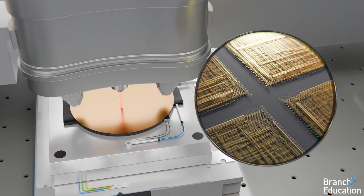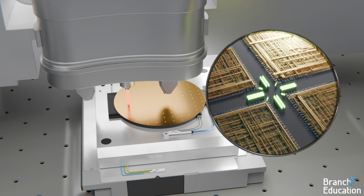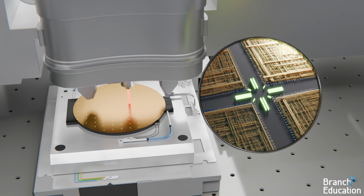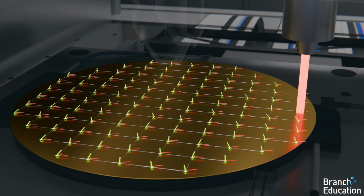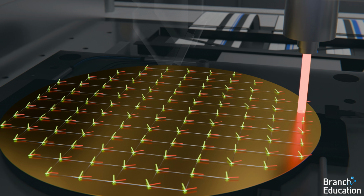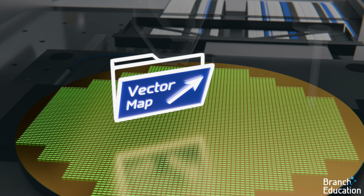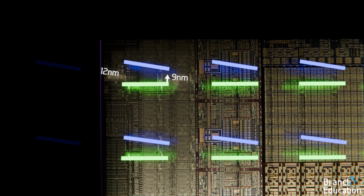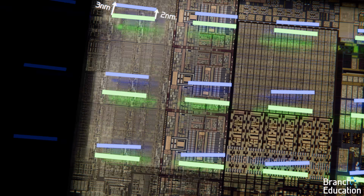On the wafer are hundreds of alignment marks, which are reference patterns that assist in determining the exact position of the earlier layers of patterns. The alignment sensor meticulously measures the X and Y positions of every alignment mark on the wafer and builds a highly accurate 2D map from the results. This map shows some regions of the wafer being biased in one direction by a few to dozens of nanometers, and another region being biased in a different direction.